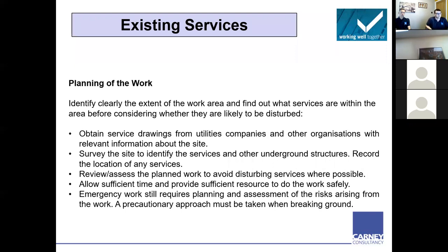So we need to look at the extent of the work area, find out what services are present, and consider whether your works are likely to disturb these services. So again, can we get service drawings from the utility companies? Survey the site, look for underground services, and make sure you're recording the location of any of these services.